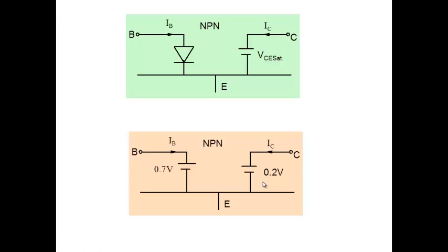All right. So if the transistor is in the saturation region, substitute this particular model and work it out. And once you work it out, you will get some IC and IB. So normally what you would do is assume, let's say, the transistor is in the saturation region, apply this model, and you will get some value of IB and some value of IC.